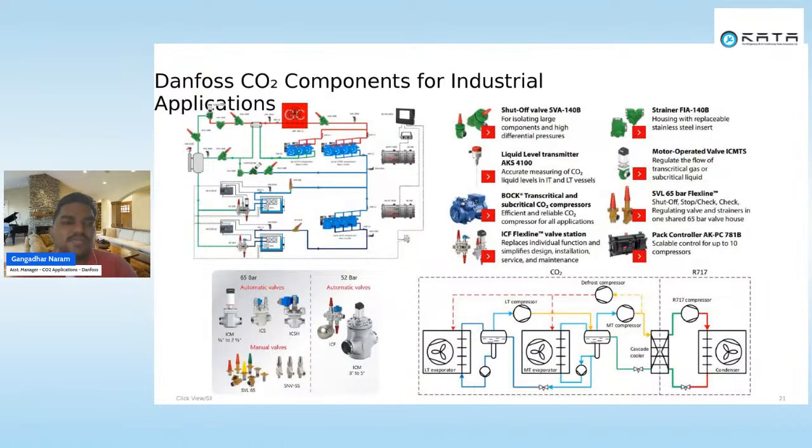So Danfoss is also future ready for the CO2 components for the industrial applications as well. Where you are having like a 1 megawatt plant or 2 megawatt plant, all these plants can be delivered with our CO2 future ready components. Nearly 85 to 90% of components are available in the Danfoss portfolio, designed for 140 bar rated applications, also when you're dealing with transcritical systems.